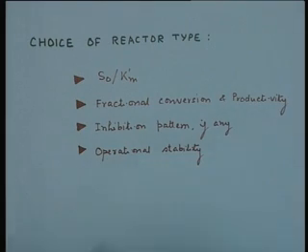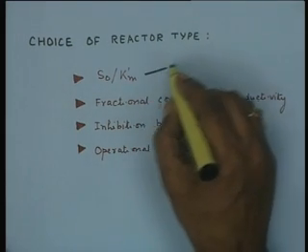We have also not considered any of the mass transfer limitations or partitioning effect in the system, and under those conditions, if you compare the two major types of continuous flow reactor system, CSTR and PFR, we have to analyze the reactor performance for a given reaction on the basis of the relative concentration of substrate to the Km value of the reaction. Basically it amounts to looking at the reaction kinetics.